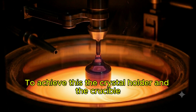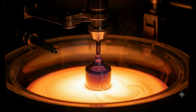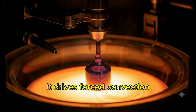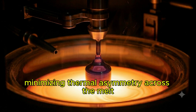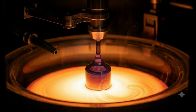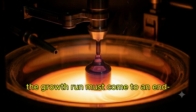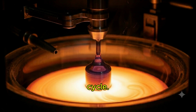To achieve this, the crystal holder and the crucible are rotated in opposite directions. This counter-rotation is essential for fluid dynamics. It drives forced convection currents within the molten silicon, minimizing thermal asymmetry across the melt and ensuring a highly uniform distribution of dopant atoms. Eventually, as the molten raw material is depleted, the growth run must come to an end, bringing us to the final step of the physical growth cycle.